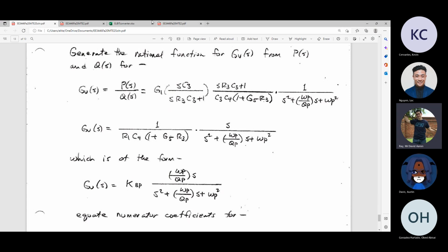So what he's doing here is you see an S in the numerator and an S in the bottom. If there was no S in the numerator, then this would be a third order system, because this S would multiply with these other S's on the right-hand side. But since technically the top S and the bottom S cancel each other out, it's just second order, because there's an S squared term, and that's the highest order it gets.